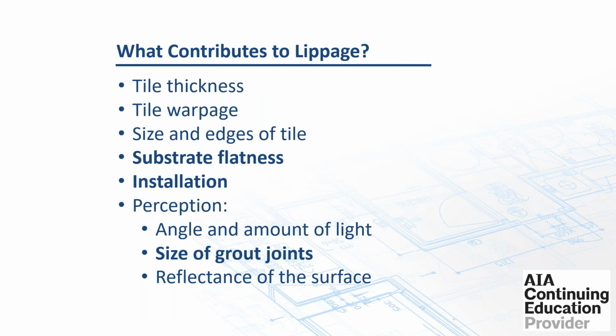All right, what contributes to lippage? Well, a lot of different things. Tile thickness. Sometimes we see patterns, and we had some tile come in from a project in Australia, from an airport, and they were saying that they were having a lot of cracking and so on. They sent us the patterns for the tile. There are 3 different types of tile, 3 different thicknesses. That makes installation very, very difficult. But in general, tile thickness can contribute to lippage.